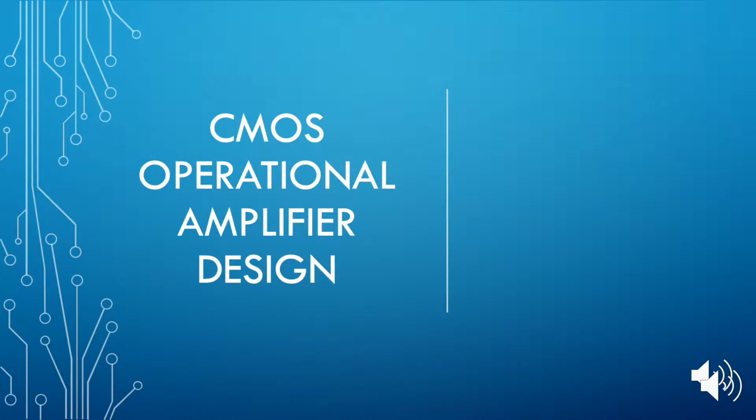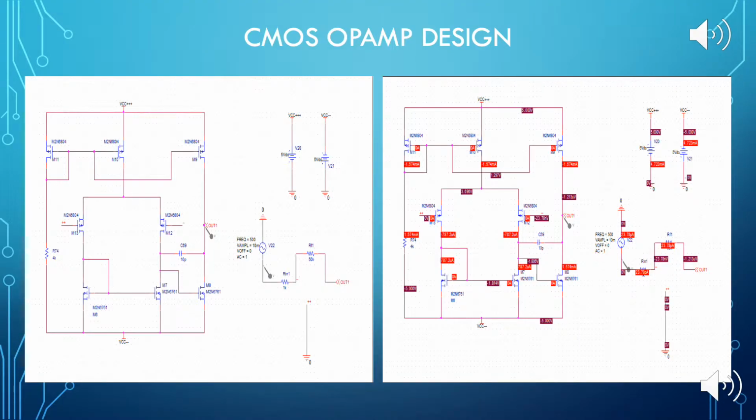Now I will discuss what I built for the CMOS operational amplifier, which was trying to get the same response out of an op amp made of MOSFETs. So this is my amplifier design. I used a schematic out of the textbook and found that it gave me close to a gain of 50 for the simulation.